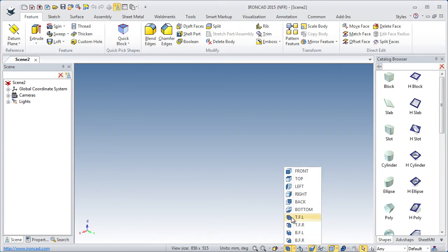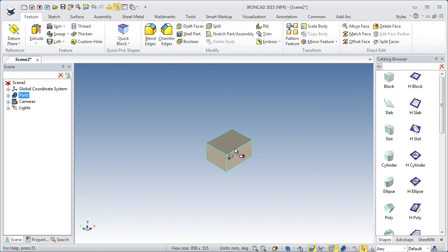And then we will change the camera view. Click on this button. We change it to top front left, so that you and I are in the same position with the camera. When this is done, we will left drag a block, click and hold, and drag it onto the scene and drop it. And then we click on the block so that we can see the size handles. We click on this handle to change the value to 50 and hit enter.